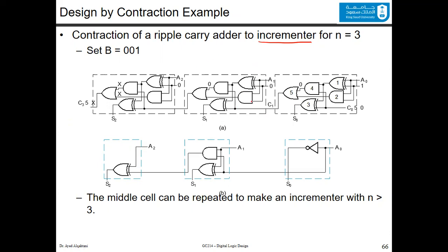Now, we do the same here. Now, we no longer have a 0. We have a carry 1. So some of the gates we will keep. Since we have a 0, this 0 will be directly going through the XOR. So we take out the XOR. And since we have this 0 going here, this 0 will be one of the operands of this AND circuit, which will cross this AND completely.